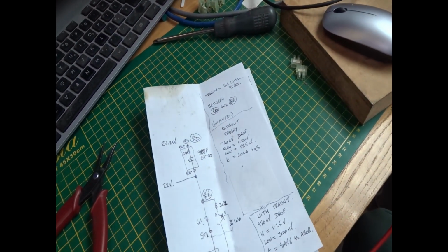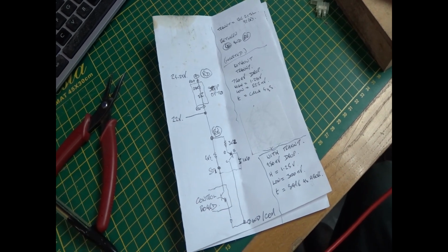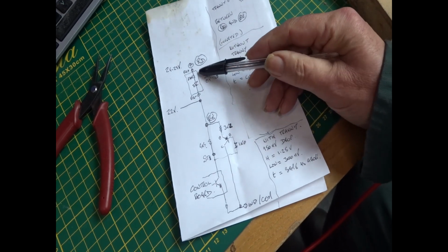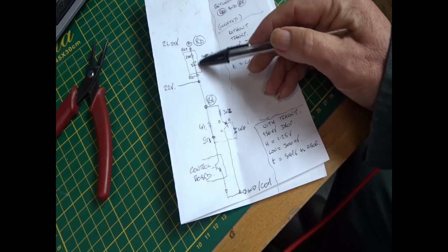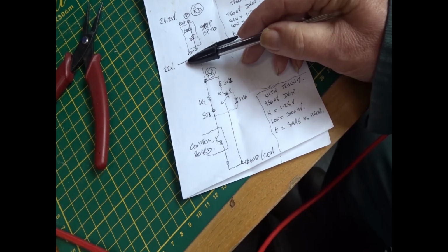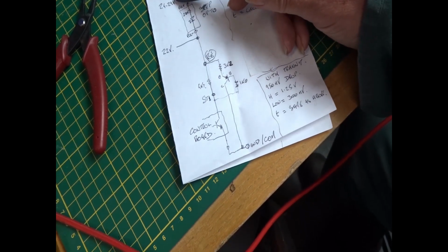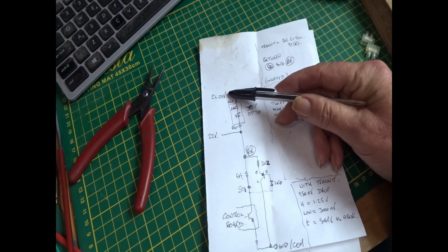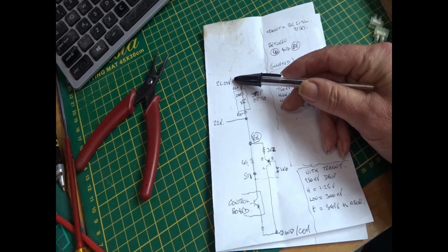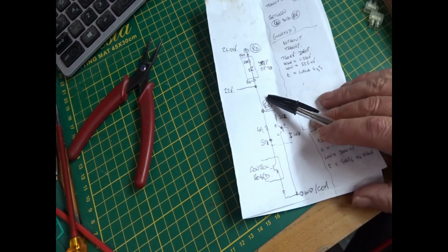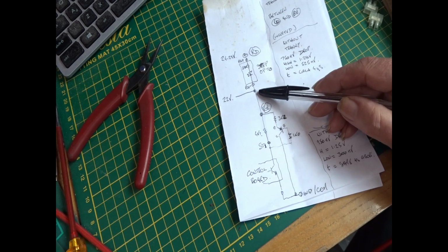So what we got? It's the stepper motor, the pulse plus and pulse minus. I'm getting about 22 volts after it. The voltage being fed to it is 24.29, which is nominally 24 volts, but let's call it 24.29. 22 volts coming out.